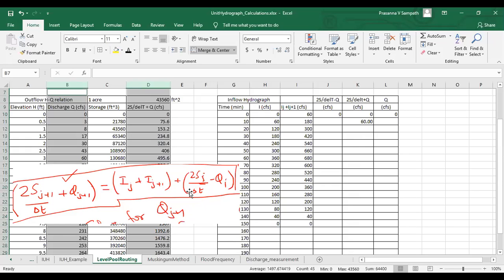See, in this particular example, we have used a simple reservoir which has an area that is not changing as a function of height. In reality, with a little change in the height, the storage may increase dramatically. But as soon as height changes, the outflow also changes, right? So you've always got to keep computing the outflow at every instant of time because the inflow is changing.